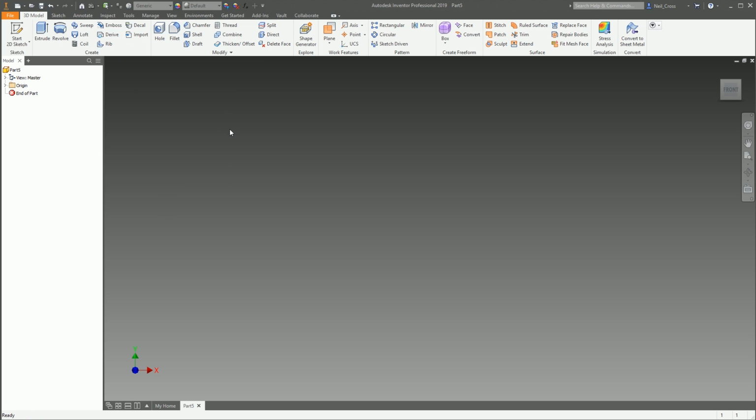If you're an ex-AutoCAD user, it's like an XREF. You're taking a model that you've already modeled and you're putting it into this new file as a starting point or a reference. So it's almost like skeletal modeling. That's one use for Derive component. And let's just stick with that one for this one. So say you're a company that makes graphics cards, right? All of your graphics cards, they wouldn't be, but just humour me, all of your graphics cards start out from the same PCB board, right?